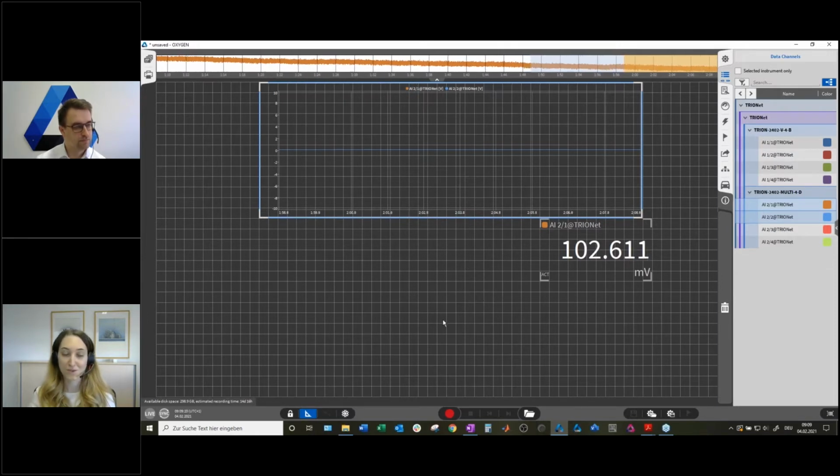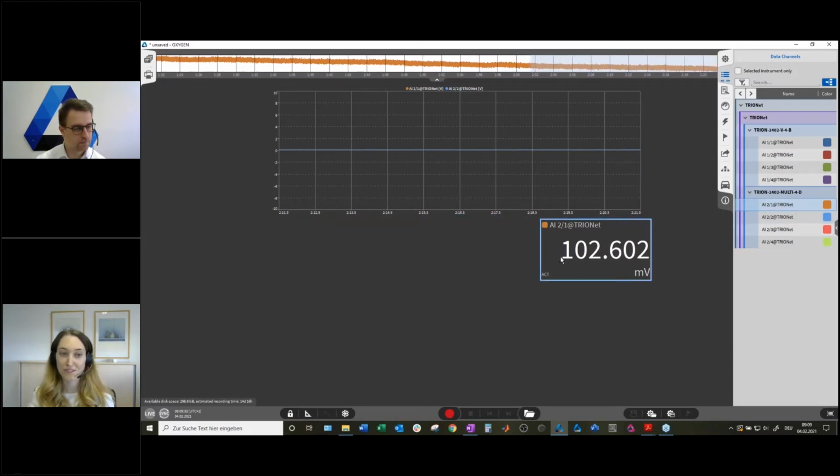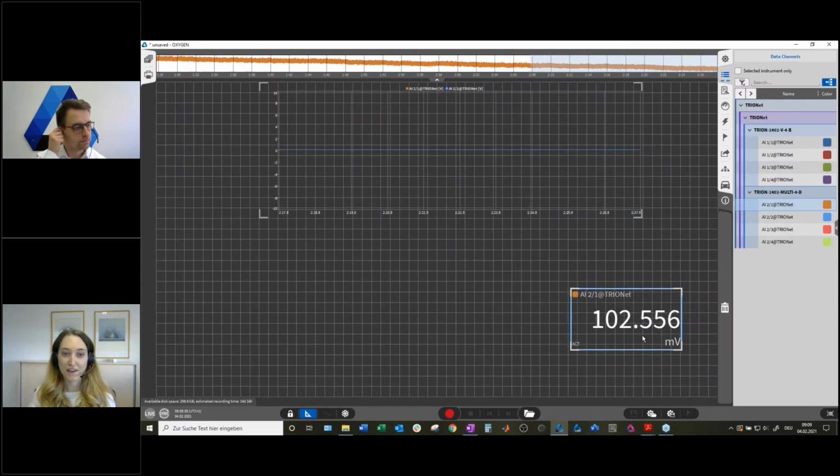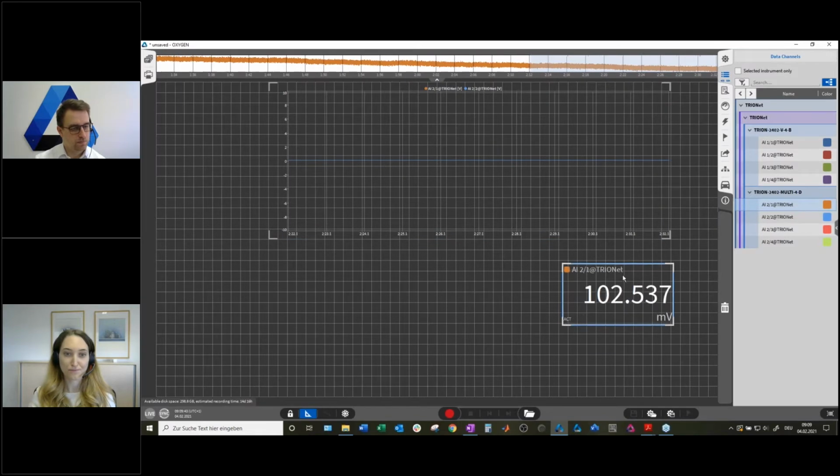So we switched to design mode, which can be enabled down here in the action bar. If I click on it, the grid disappears, and my instruments are fixed. I cannot change them anymore. If I enable it, the grid appears and I can arrange my screen again the way I would like to.